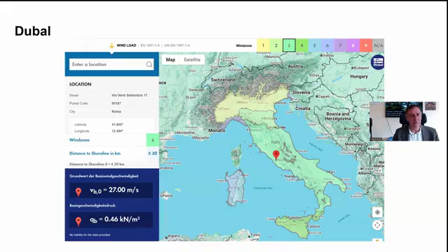In those areas, we recommend you to consult with structural engineers and ask what basic wind velocity they are using for mountains. In mountains, when your tree is on a hilltop, but it's not in the practice in the Alps, the basic wind velocity is much higher, relative to the deep valley, where the wind speed can never be high.